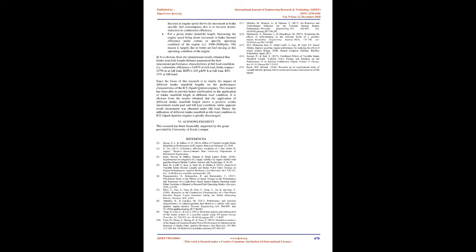1. For a specified intake manifold length, increasing the engine speed brings about an increment in volumetric efficiency at part and full load condition. This is due to higher speeds giving higher vacuum at the intake port. While, for idle load, increasing the engine speed reduces the volumetric efficiency due to deterioration in combustion quality.